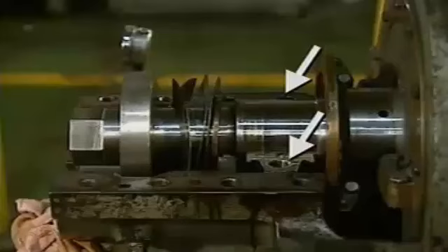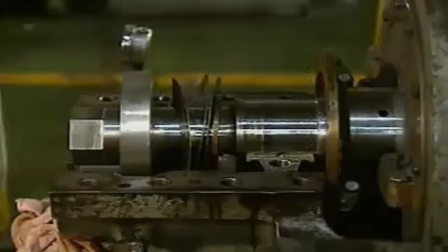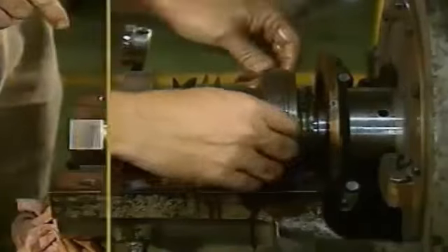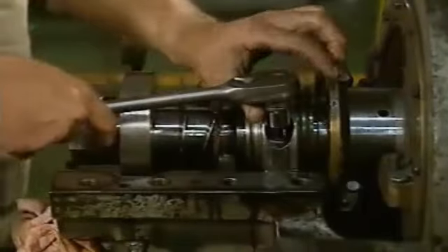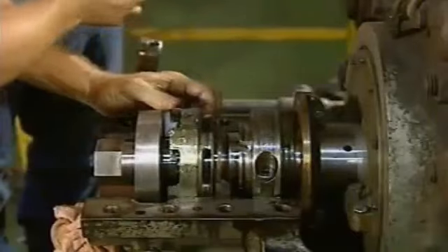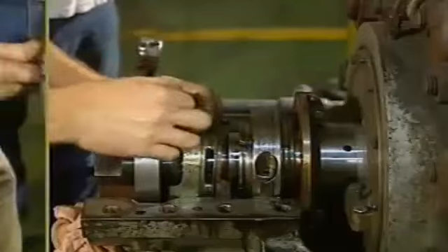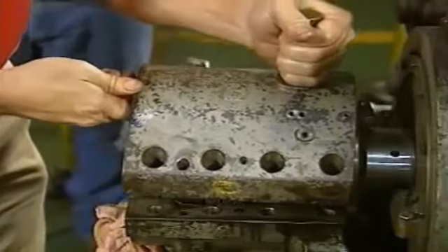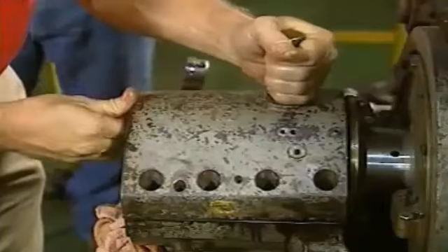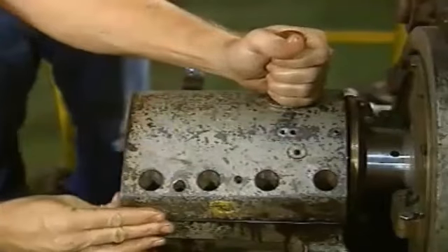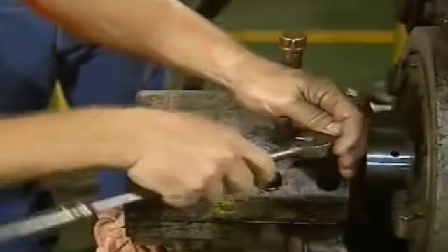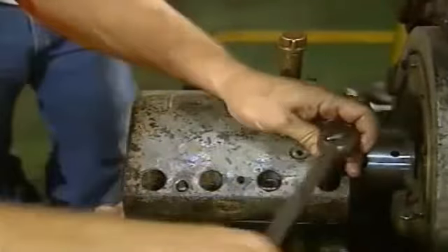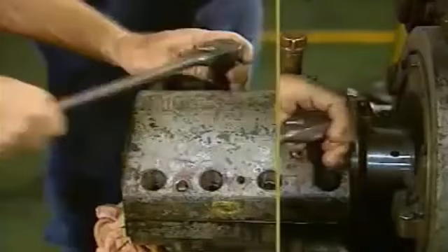The lower shell of the bearing is installed first, and then the mechanic puts the upper shell in place. Once the bearing shells are properly positioned, the mechanic installs the bolts that hold the shells together. Next, the thrust bearings are installed on the shaft. Then the bearing housing is reassembled, and the housing bolts and guide pins that secure and align the housing are installed. Finally, the mechanic tightens the housing bolts, following a pattern specified by the manufacturer to make sure that they are tightened evenly.